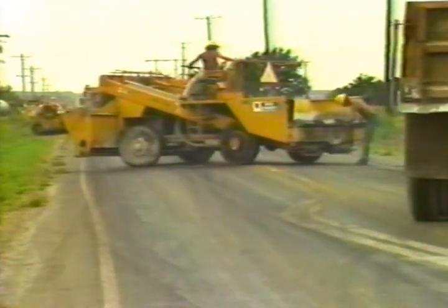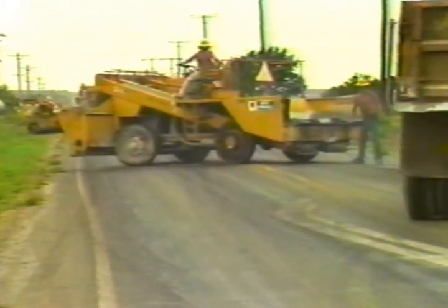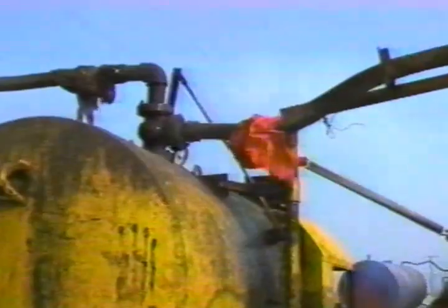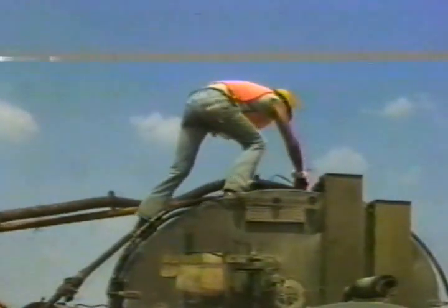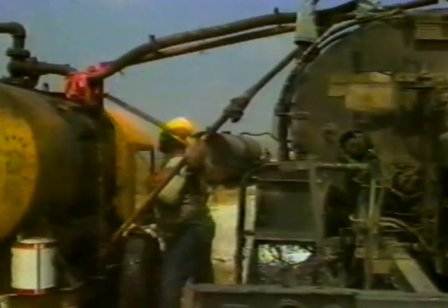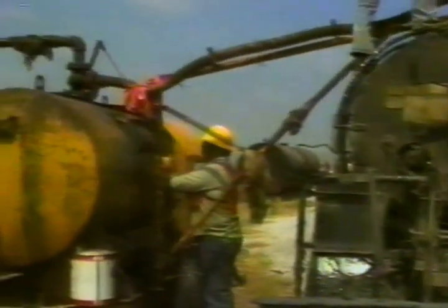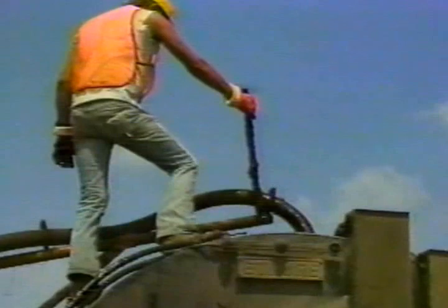The most serious problems are likely to occur at the asphalt storage facility. Overheated flues, a half-filled booster pump, or return lines containing oil pockets can cause explosions, resulting in severe damage and injury. Premature opening of the valve during distributor loading can produce an unexpected surge of hot oil, creating a big mess and maybe severe burns.